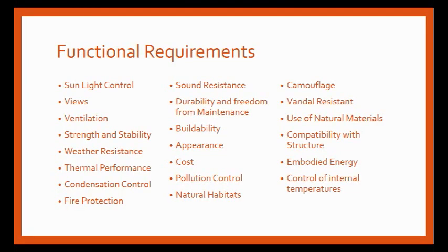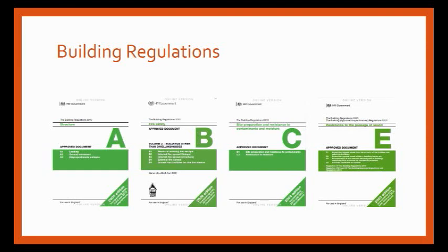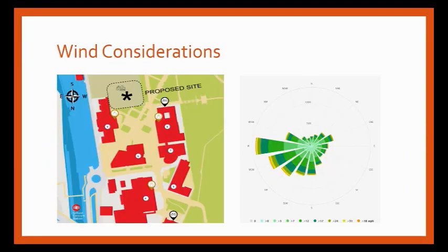Consequently, cladding is subject to functional requirements that ensure the scope of the design is appropriate to the determination of potential risks and meets all the building regulations, which include Approved Documents A, B, C and E. According to the Building Envelope Authority, wind has the greatest potential to cause damage to cladding, and due to the 4-storey building being located in the UK, weather can be quite unpredictable.